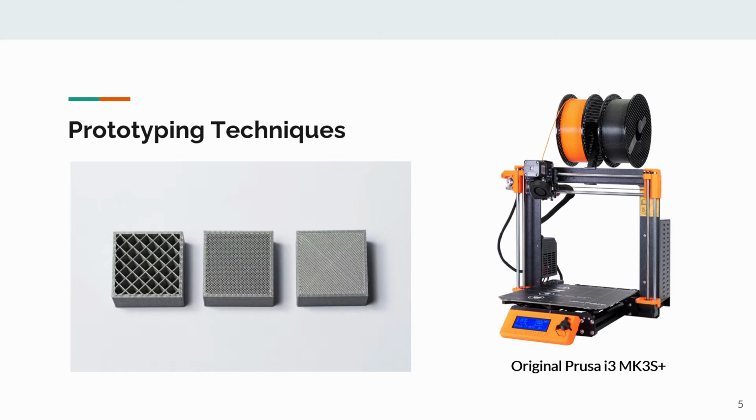technique. The choice of using a 10% infill technique allows us again for a quick turnover time, but inevitably introduces discrepancies and differences between the response of our actual rocket piece and that of test sample data. This is despite using test sample data that was printed using the same infill techniques. This of course is due to the fact that when printing on 3D printers, the volume of infill is a function of its geometry and wall thickness. We will go into further detail in further slides denoting this deviation and any discrepancies we saw during testing and that of the modeling phase.